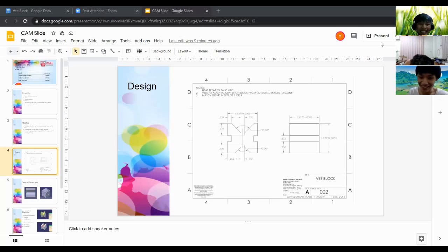We start to generate the hole where the length will be 0.77 from the top plane. And next we'll do the same for the bottom part, but with a different dimension, which is 0.484 for the side extension, but the angle will be equal to the top plane, which is 45 degrees, and the distance from the bottom plane to the middle hole will be 0.52.